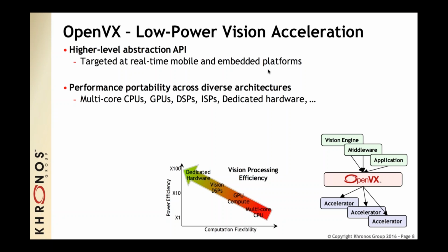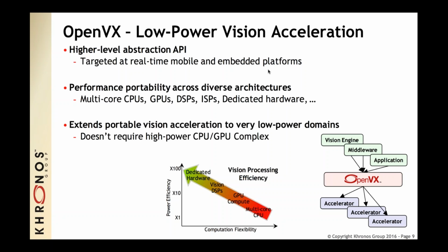Each subtask can run on the most power-efficient hardware the system has. If there is a special ASIC for some task, the system selects that unit instead of the very general but power-hungry CPU or GPU. Algorithms that run efficiently on vectorized integer-based vision DSPs run on those. Tasks that cannot be run on the most efficient units can be run on the GPU or CPU, but if a better unit is available, those more general processors can even go to sleep to save power.